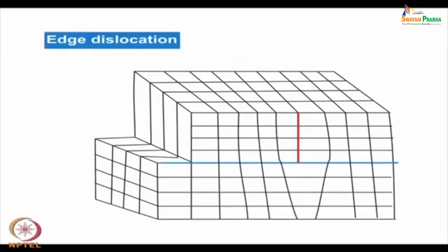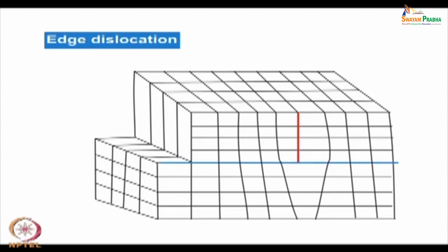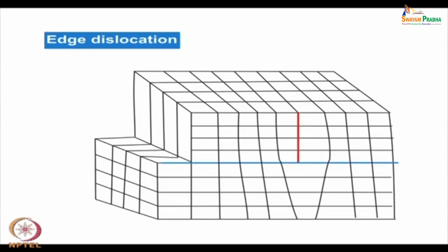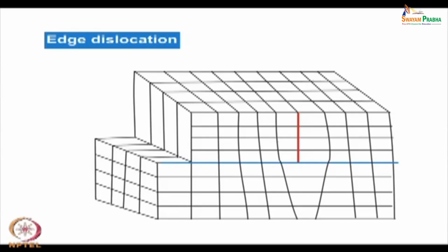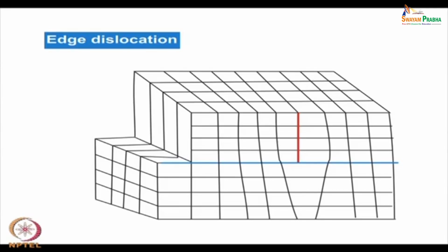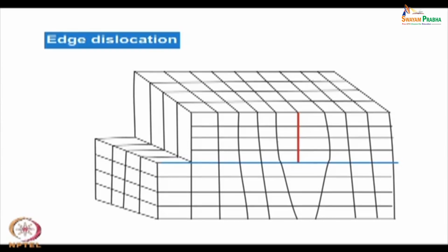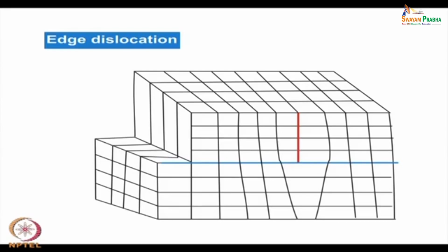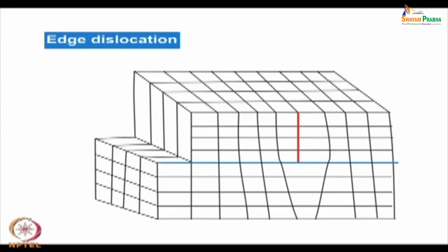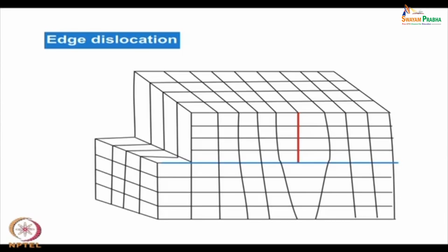With this background, let us try to see what actually a dislocation is. Dislocation is related to the deformation of the crystal. It is plastic deformation, a permanent deformation, where the dislocations come up. For elastic deformation, where there is no permanent deformation, there is no question of dislocations being formed, or dislocations are not needed. This concept of dislocation is irrelevant there, whereas only for the plastic deformation part, the concept of dislocation is very, very important.